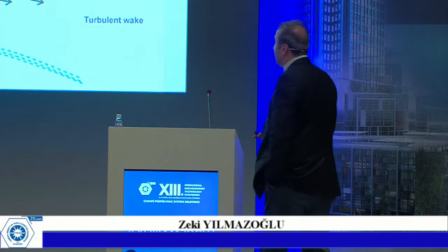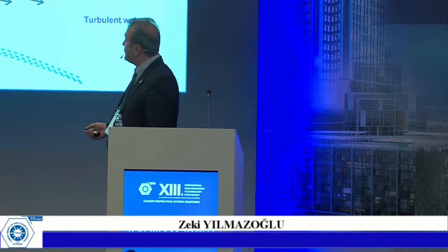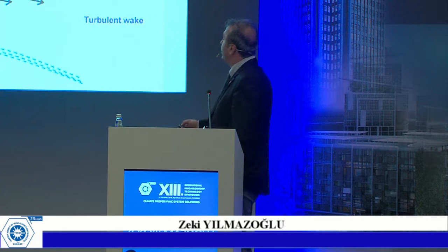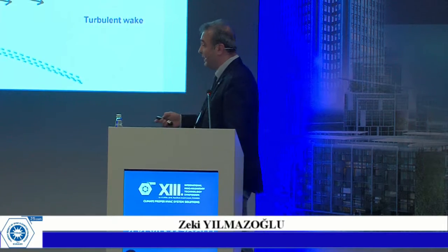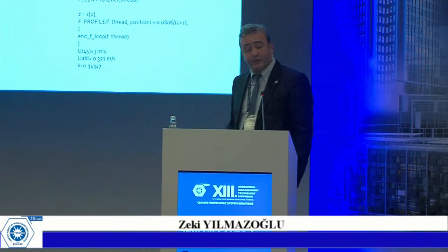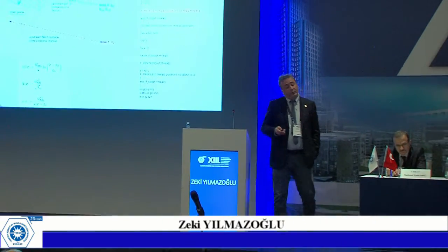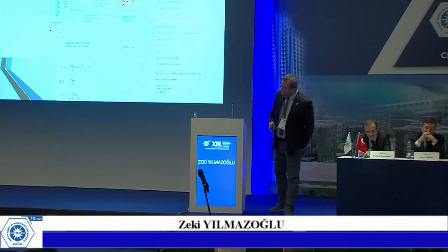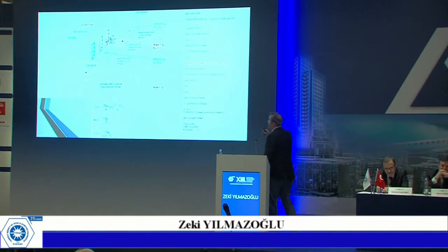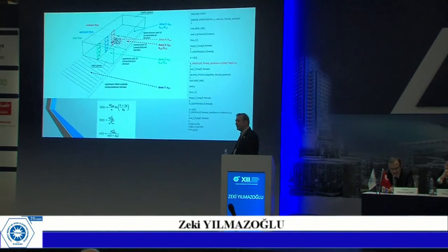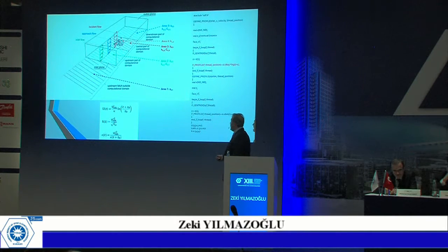Okay, in the modeling, as I said in the beginning of my presentation, atmospheric boundary layer and horseshoe effect and pressure on that side should be taken into account, as you will see from the results. Atmospheric boundary layer modeling needs a surface roughness factor, and the velocity profile, turbulence, and kinetic energy dissipation have to be in logarithmic scale as shown in here.